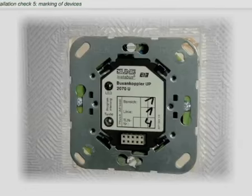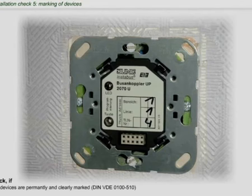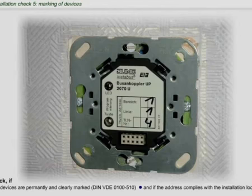All bus devices should be clearly identified by marking them with the complete physical address. This also applies to flush-mounted devices, built-in devices and distribution components. It must be ensured that the marking complies with the actual point of installation.